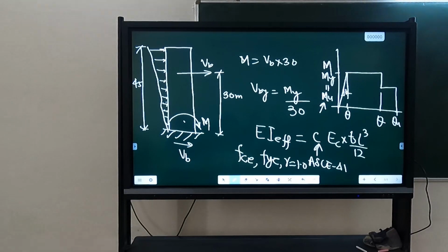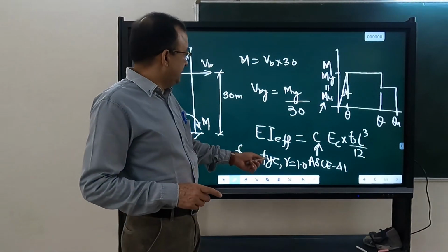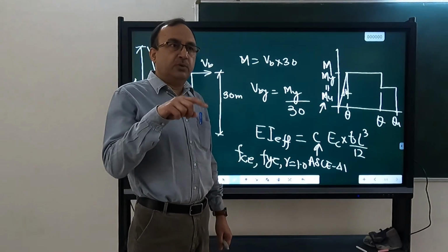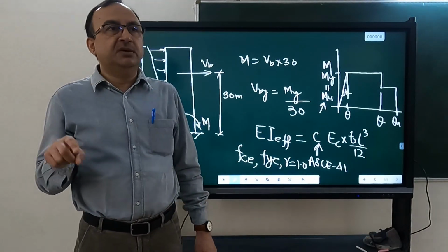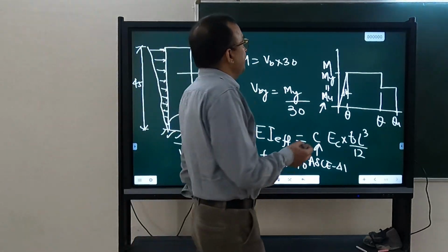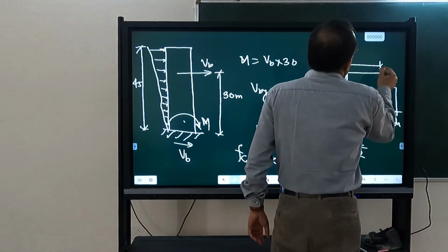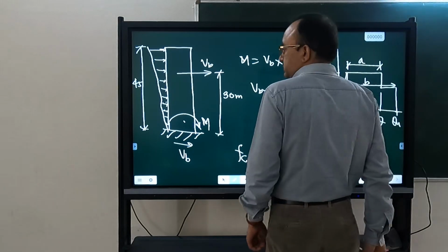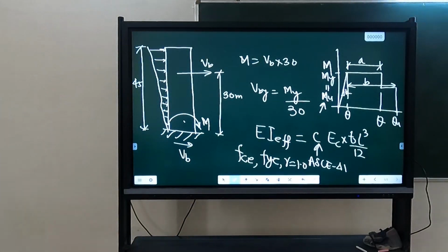Okay, and expected cube strength, not the corrected strength of the structure, because those correction factors are built into those expressions. So only FCK you will replace by this, FY you will replace by this, and wherever those factors 1.5 or 1.15 or 0.87 are there, you will use 1. Okay? And then AC41 gives you values of A and B. You will take these values of A and B from there.